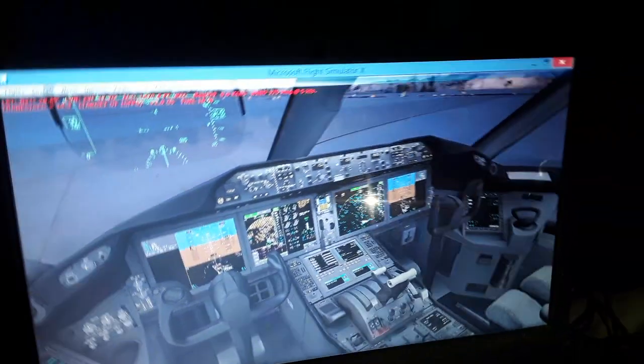Also, as we fly the aircraft, we have the outflow valves. I'll show you the outflow air. So we have outflow pressurized air from the 5th and 9th stage of the engine, and also bypass air from the front fan. We use the outflow valves to regulate the pressure. This is also done automatically using the FADEC computers. They automatically set the position of the outflow valves to keep the pressure regulated. If we have an overpressure or an underpressure, the outflow valves can open or close to a higher or lower position to regulate the pressure.